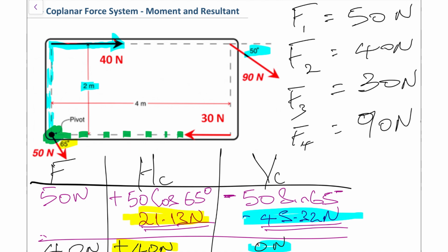Now, for the next force, which is our 90 newtons, I'll just use this red to highlight it more. Right there. It is, in fact, that looks messy. So I'll just use a different color. I'll use yellow to highlight it. There we go. So that 90 newtons, remember previously we calculated two components for that 90 newtons. And those components, we already know the values, which we'll use shortly. I'm just going to show you now how to understand the perpendicular distance of them. So for the vertical components, let me clear all the markings so we can see this.